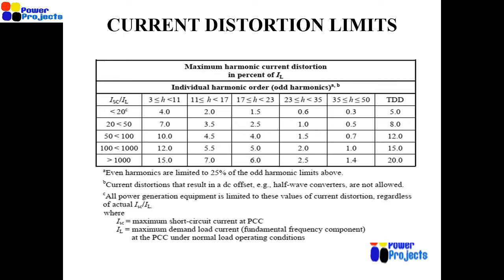The question from Aman: why reduce the harmonic distortion? If the harmonic distortion level is within the limit, then there is definitely no question of reducing it. But if the harmonic level is beyond the limit, then definitely you need to reduce it, simply because it has quite a lot of ill effects. It increases the current, increases the temperature, reduces the life of the equipment, and causes more malfunctioning of relays.